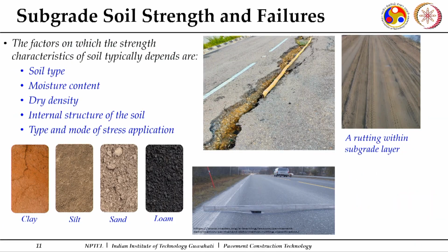in the field also. Now, the characteristics of the individual materials which we use in subgrade construction depend upon various internal factors. One is soil type; in broad categories, granular, clay or silty soil. We have different classification systems, and I will not go into the detail of it.